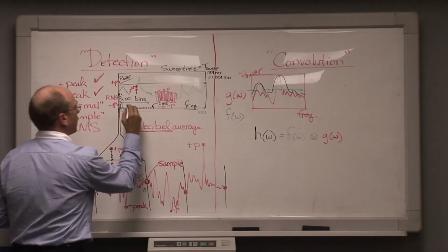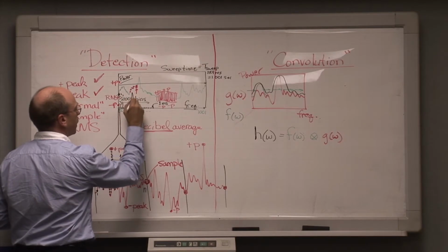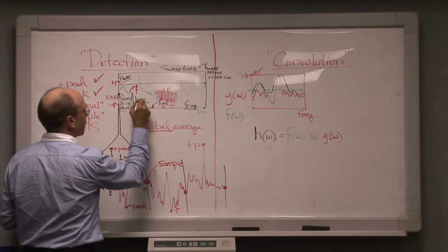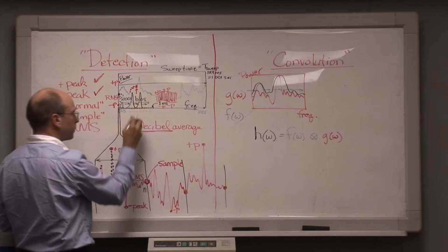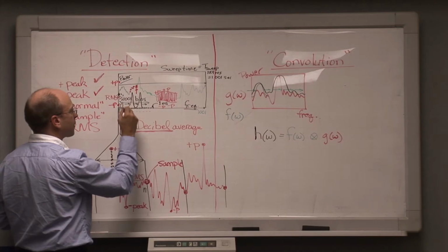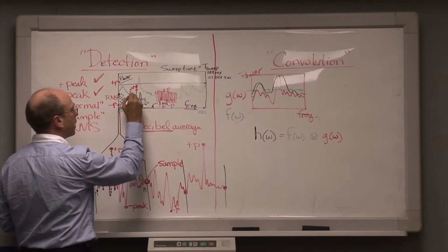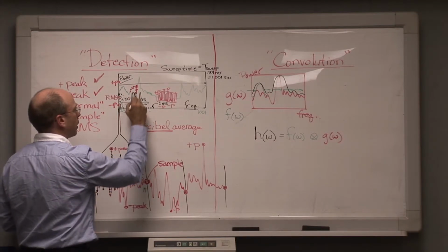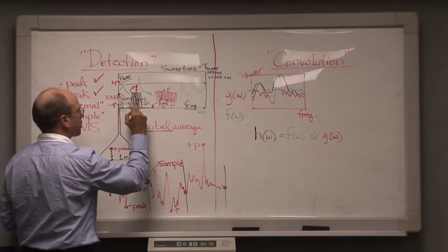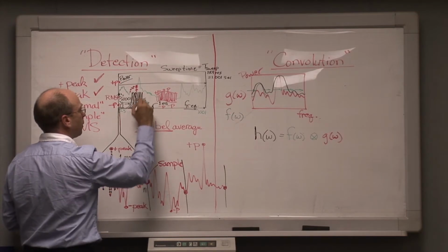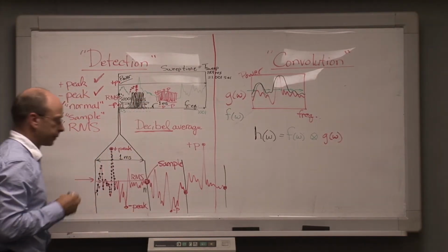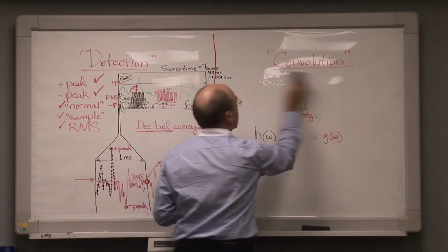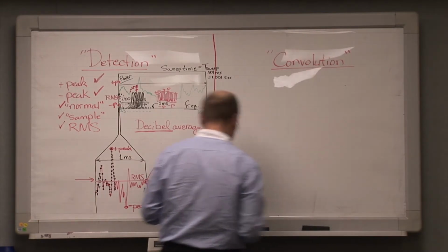Secondly, in order to get across any non-zero amount of spectrum on, for example, this display where we're moving a filter across, if we had a 0 width IF filter being moved across, like so, then it would take us an infinite amount of time to step this filter across in such a way that we would get successively overlapping steps like this that would allow us to sample the spectrum without gaps. And I'm going to explicate a little bit graphically how this works.